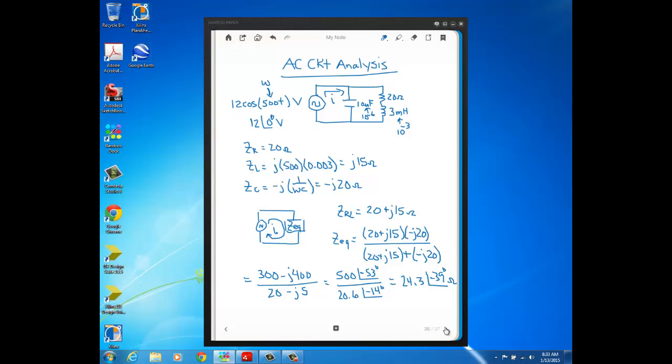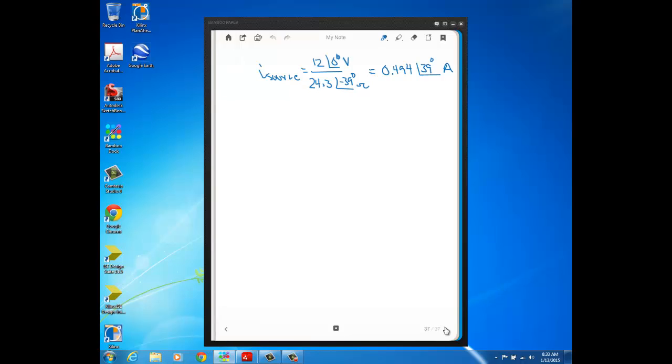So just like in DC circuits, where you have current divider, remember the general form is to get the current through a parallel resistor, you take the current flowing into the parallel combination times a ratio of resistances, where Req divided by R, where R is the resistor you want the current for. Well, AC current divider is the same form of equation, it's just you have impedance instead of resistance.